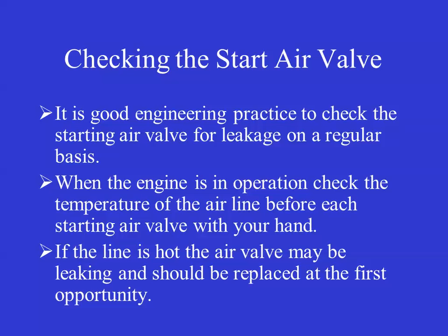On the start air valves, it is a good idea to check these on a regular basis. What can happen is start air valves can burn and start to leak. And if they leak, then when the engine's running, those combustion gases can get into the start air line.